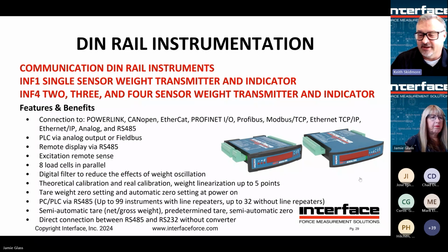However, it is possible to get the individual A to D counts for each channel. And so we have a number of customers who actually do want to look at each channel individually. Say with a 3-axis sensor, you want to have each axis hooked up to a different channel. In this case, you could have raw scaling that can be pulled over the field bus. And that might be, say, 2 million counts equals 2 millivolts per volt. Then in the processing, you could apply the scaling factor and convert to engineering units. So that's certainly possible, and a number of customers are doing that. But just keep that in mind. With the 4-channel ones, if you want pounds coming out of it, it's going to be a sum of the 4. These can have remote.